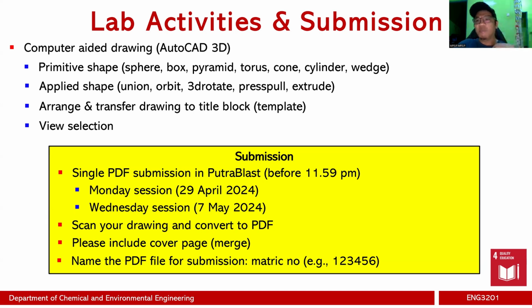And after you have prepared your drawing, you just need to arrange your drawing first and then transfer it into your title block. But if you already have your own version of a template, then it's much easier. After that, you just choose your views: isometric, northwest, southeast, southwest, perspective, parallel, projection, whatever, as long as it seems to be nice in your title block.